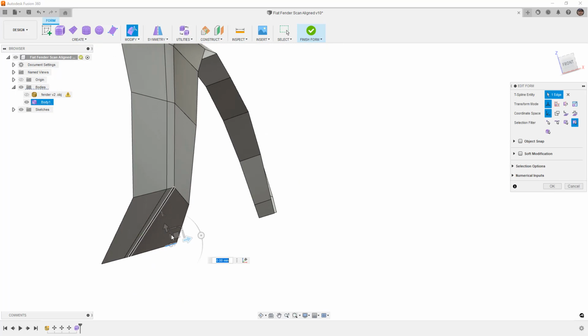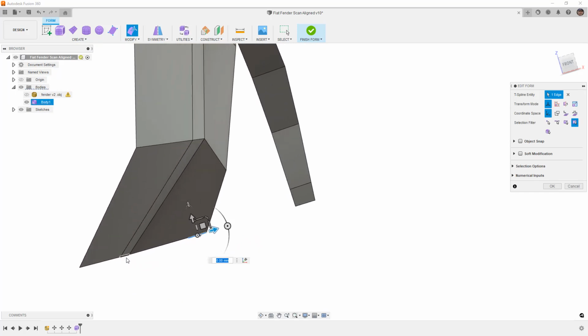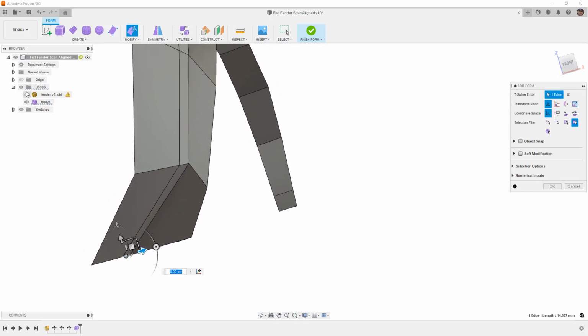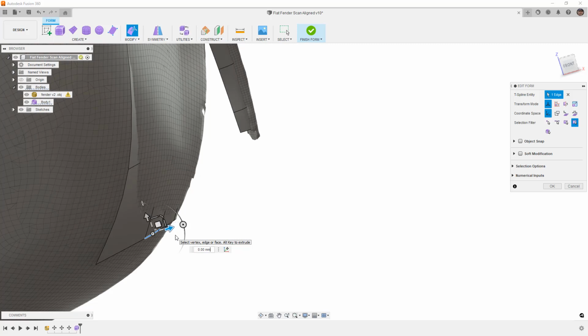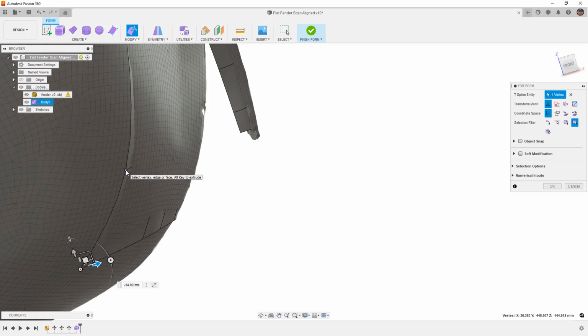It can be kind of hard to see when we're actually taking a look at the mesh. So I'm going to hide it, select that point, and then I'm going to pull it out in the X direction. And then take a look at the smooth display. So that vertex probably needs to go in a little bit. And this one probably needs to go in a little bit.